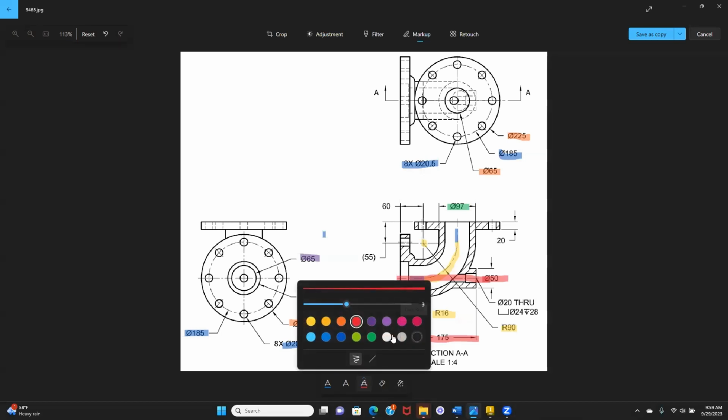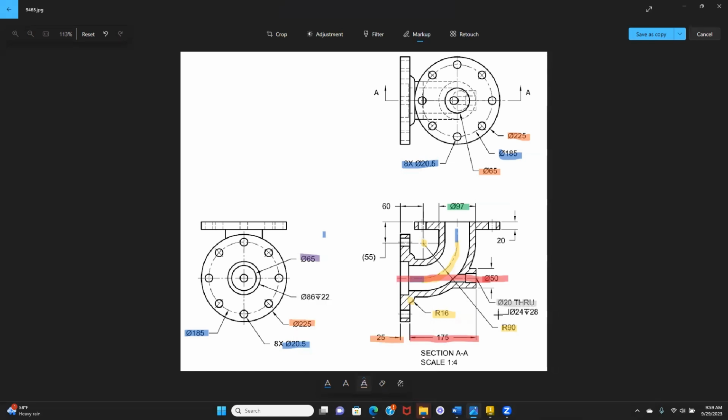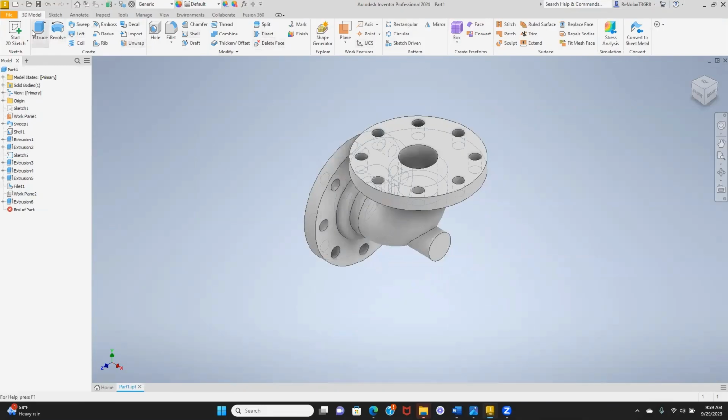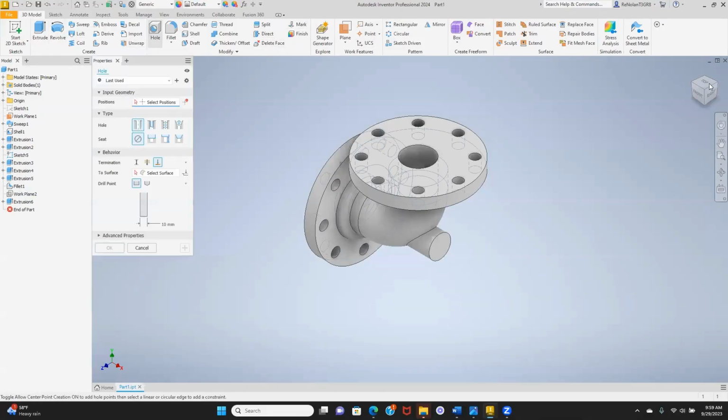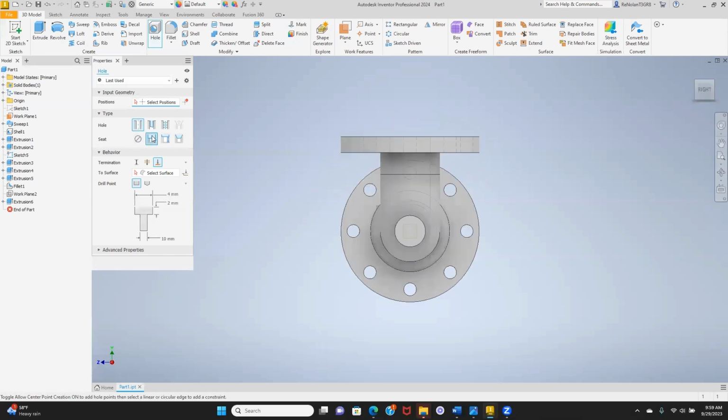Now that we have the base of our nipple, the rest of it should be a little easier and things that you're a little more familiar with from our last example. We're going to add in this hole here. We want a countersink of 24 at a depth of 28, and the remainder will be 20 through the length of the rest of the pipe. Again, this is all in millimeters. Everything I'm talking about is in millimeters.